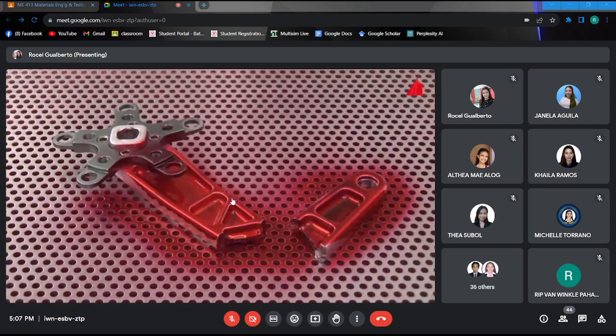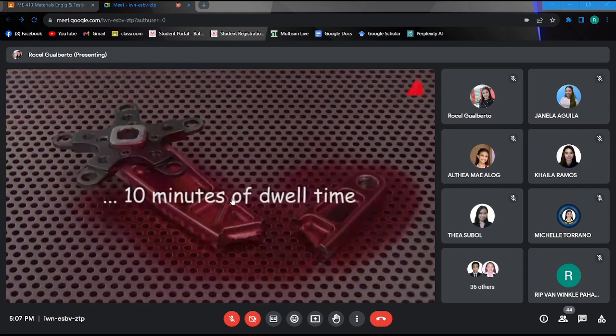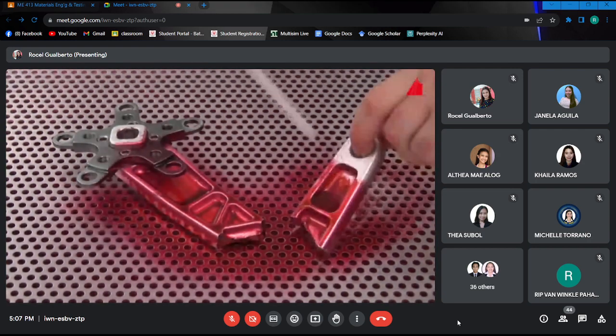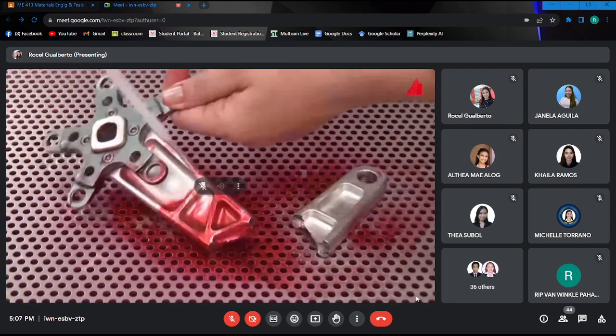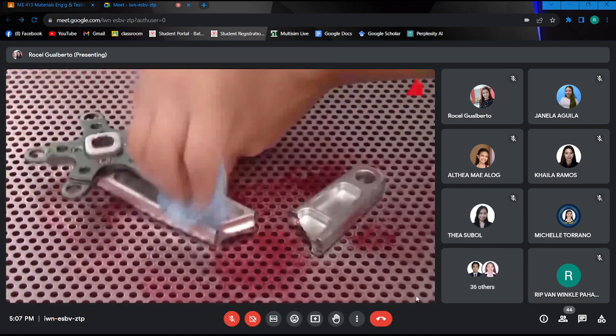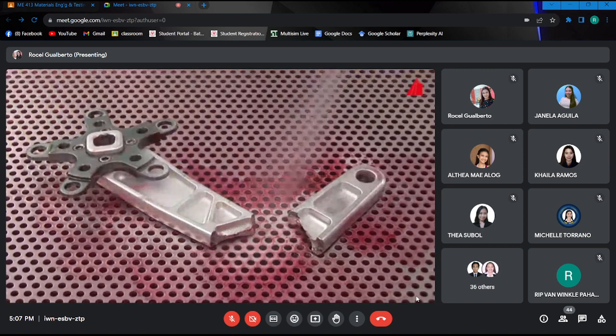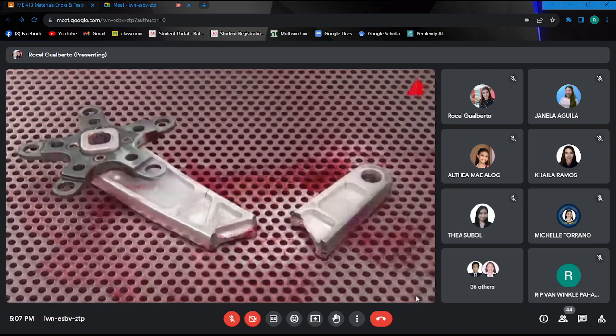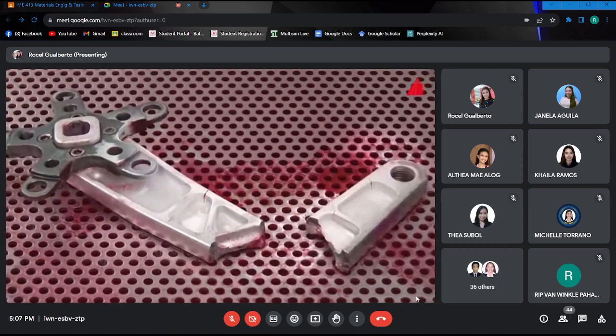Spraying with penetrant, allowing to soak, rinsing, drying, and applying developer. Clearly, additional cracks are indicated on the fragments.